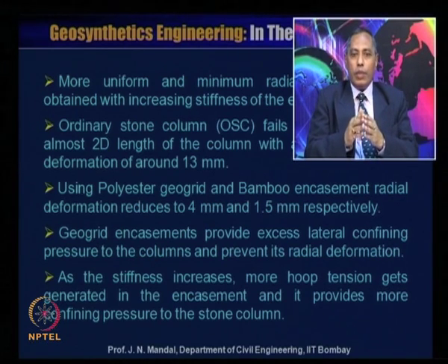Now, geogrid encasement provides extra lateral confining pressure to the column and prevents its radial deformation. As the stiffness increases, more hoop tension gets generated in the encasement and it provides more confining pressure to the stone column.